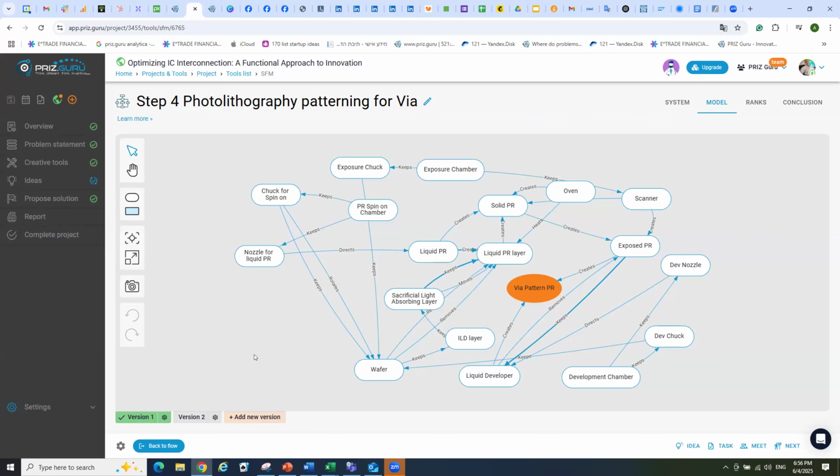So you could immediately put your current product into a function model and say, look, if we got rid of the welds and made a one-part fuel nozzle, almost like a humongous car fuel injector, you could get rid of all those welds, parts, inspections, failure modes, and all those places that can potentially cause issues and break.